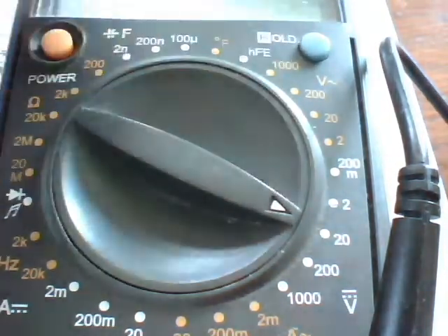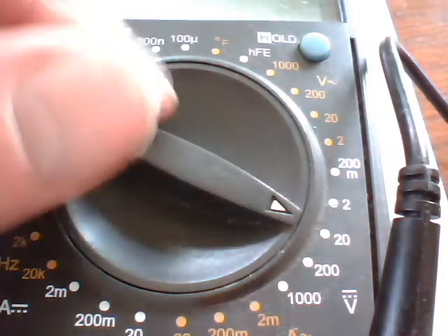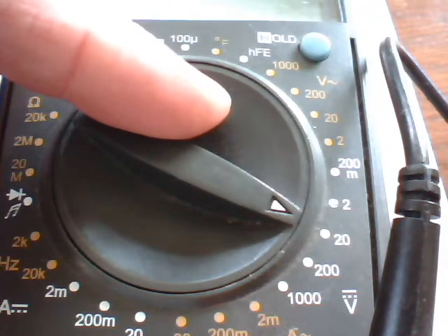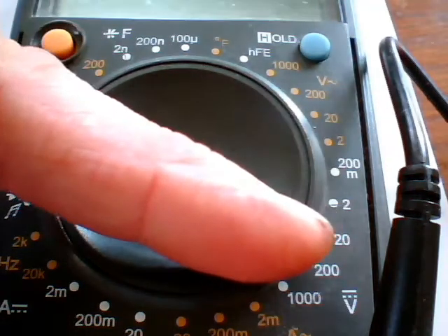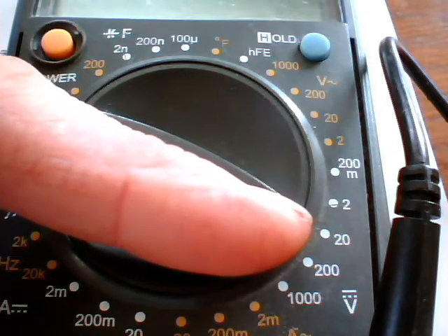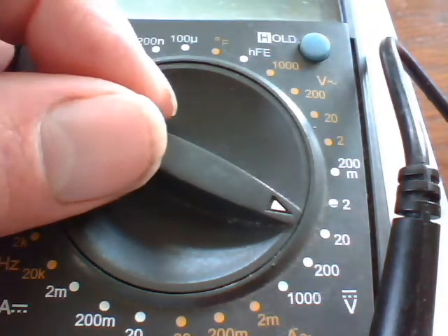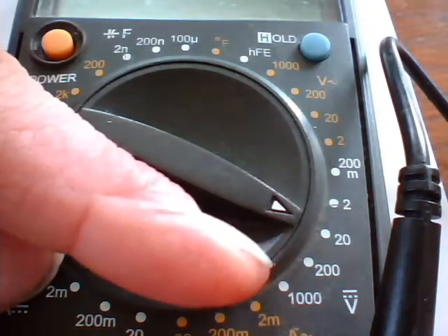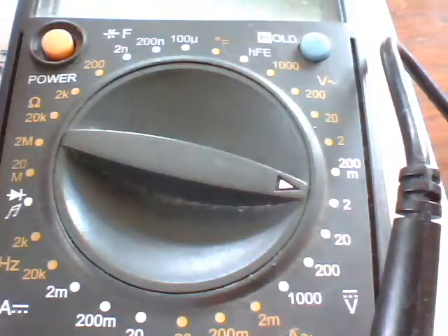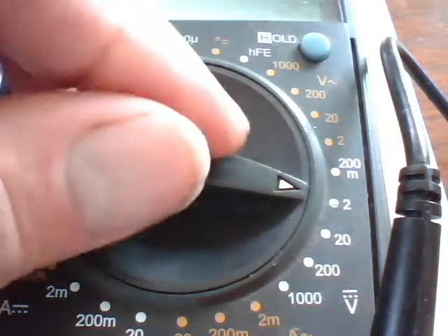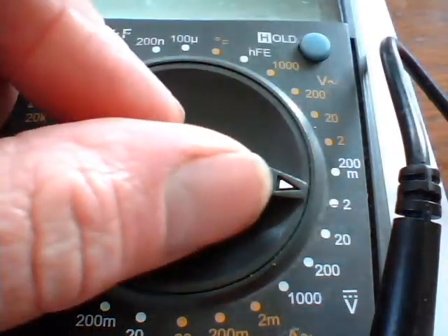So you can just flick this to whichever range you're going to measure. Usually the 20 volt range will be the best for measuring the usual batteries and car batteries, anything up to 20 volts. This value is the absolute maximum value that it will read. So if you try and measure something that's 21 volts, then this won't do. You'd have to move it onto the next scale. Likewise, anything bigger than 2 volts, then this scale would not be good. Anything smaller, 1.5 volts, for example, that would be fine.